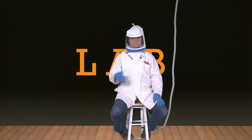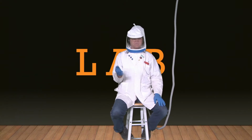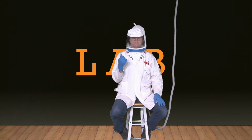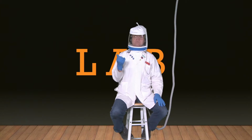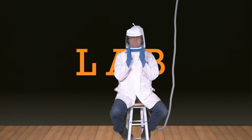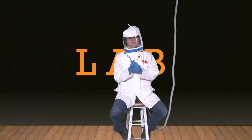Now, the funny thing about this valve is when you're opening it and closing it, yeah, we can count the number of turns or quarter turns or half turns, but that still doesn't give us an accurate representation of the amount of gas going out of the chamber, because the vacuum is going to vary with the volume of gas that's already in there.